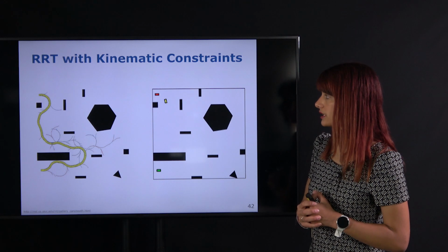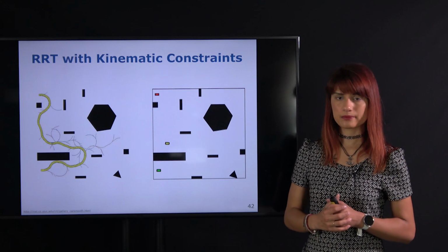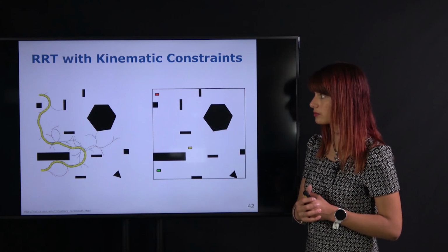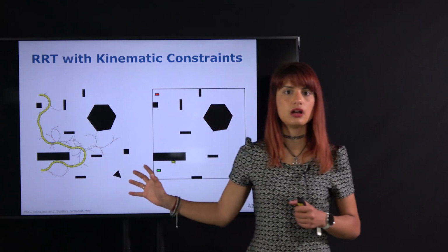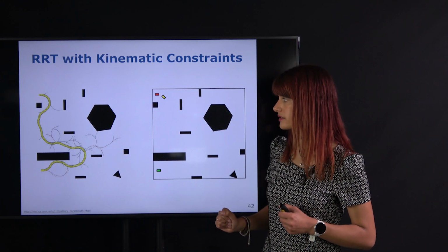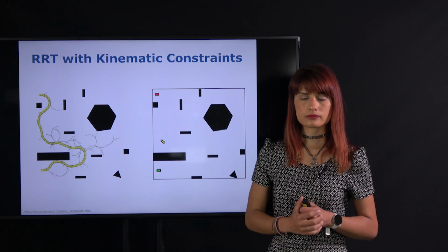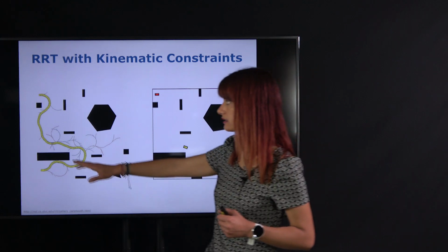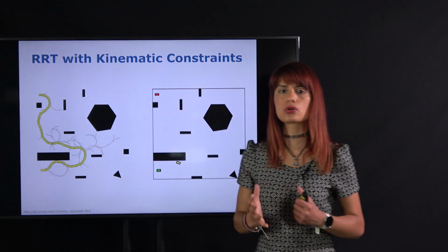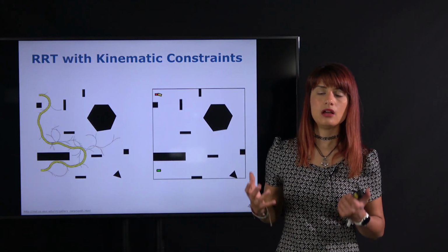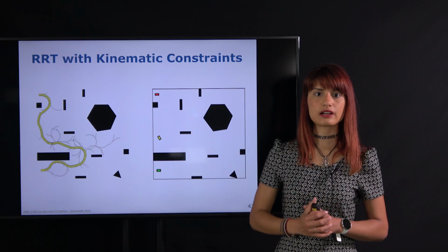On that note, looking at our RRT paths, we noticed that they're definitely not the shortest paths. Just like the probabilistic roadmap, the more we sample, the more likely we are to find a feasible path, because eventually the RRT and other tree-based planners that operate on similar principles will explore the space densely. However, a drawback here is that if we sampled this path and we found the goal, we're basically done. So we have no concept of how we can actually improve this path, how can we make it shorter, and how can we make it more optimal. This is the question that we tackle next.